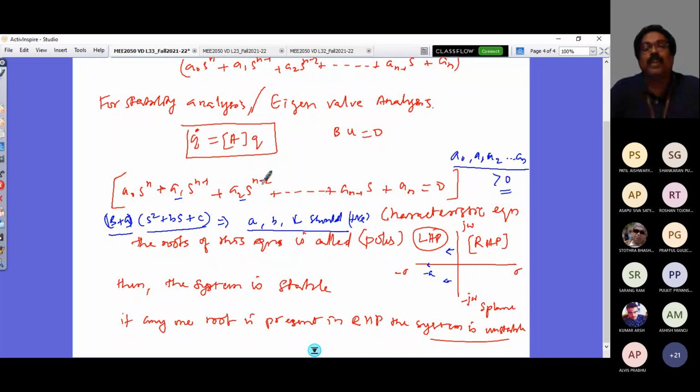But the question is, if it is found absolutely unstable, is it possible to convert it into a stable system? If so, what are the conditions that should be imposed? It is necessary but not sufficient, so what sufficient addition or modification can be brought into the system? That's what is proposed by the Routh stability criterion. The limitation of this condition is that it will be suitable for linear time invariant systems alone, and you would see that as far as relative stability is concerned,